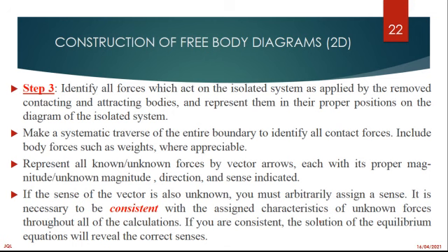Step 3. Identify all forces which act on the isolated system as applied by the removed contacting and attracting bodies, and represent them in their proper position on the diagram of the isolated system.